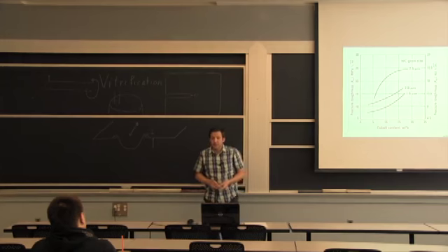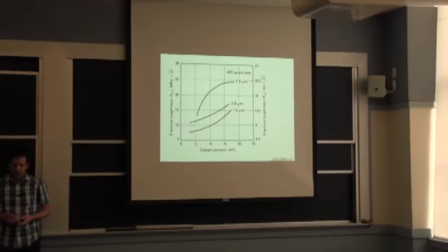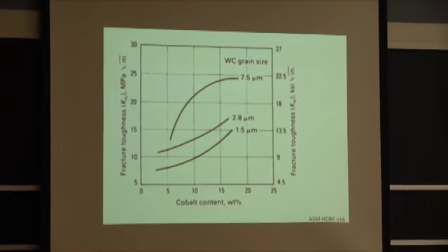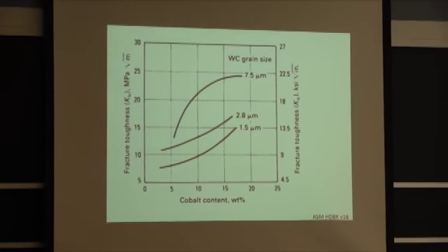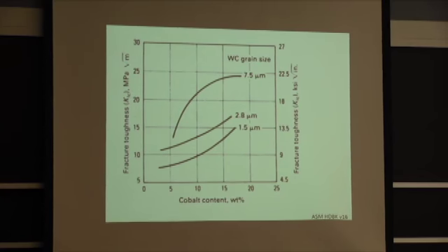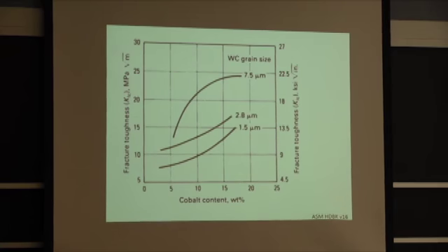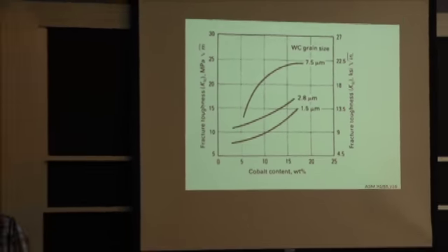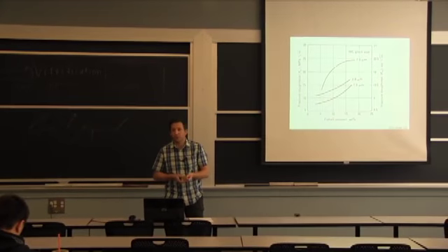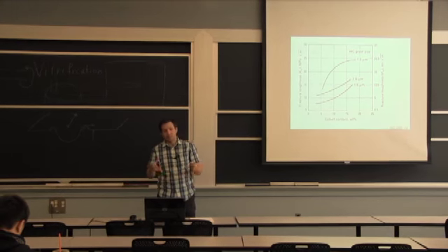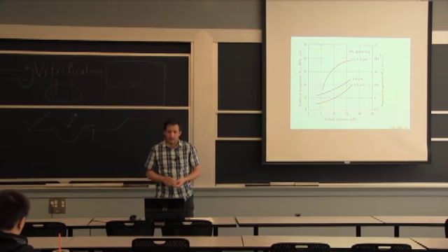I'm showing here the fracture toughness of essentially a tungsten carbide with cobalt. So this, it does go above 15. So if we wanted to have fewer issues with wear in general, we would try to use more of this cemented tungsten carbide. But there is a cost, because it has the corrosion resistance, it has a decent toughness, it has excellent wear resistance, about the same density. But there's a cost associated to it, and in the end, if you can use it as an insert, and that's what they do even for drill bits. In general, not the whole drill bit will be the cemented tungsten carbide, but you'll have the specific part that is going to be cutting that will be.